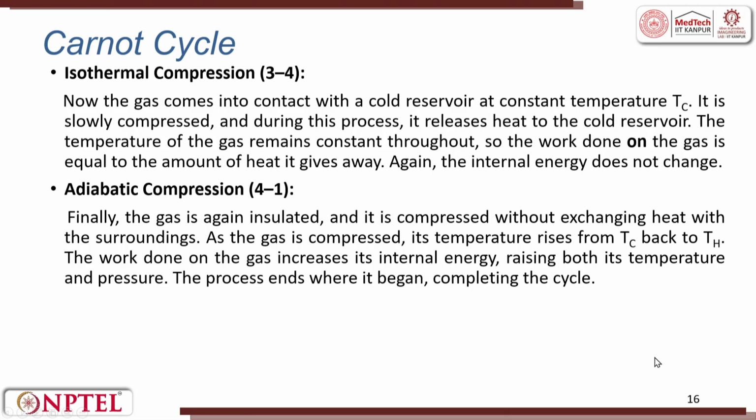Next is isothermal compression, 3 to 4. Now the gas comes in contact with the cold reservoir at constant temperature Tc. It is slowly compressed, and during this process it releases heat to the cold reservoir. The temperature of the gas remains constant throughout. So, the work done on the gas is equal to the amount of heat it gives away. Again, the internal energy does not change.